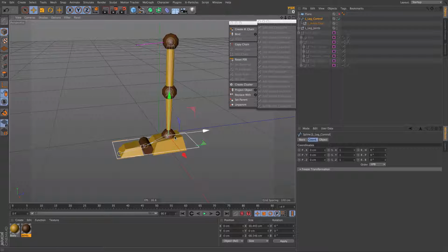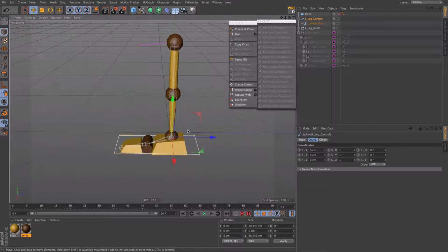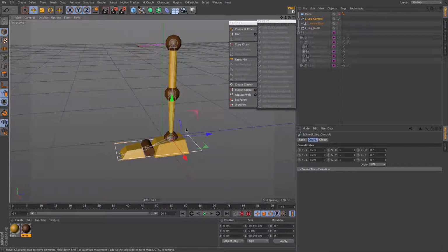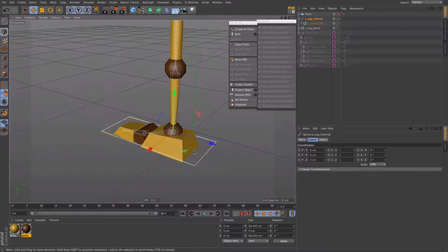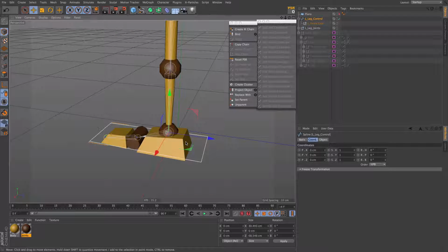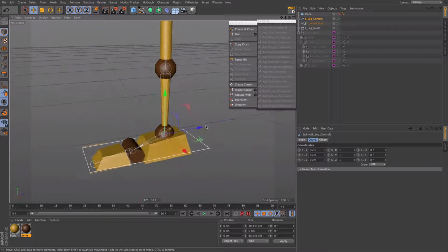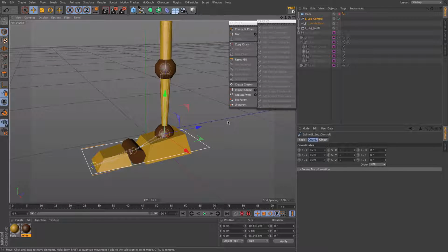Now let's make an inverse foot setup. What is an inverse foot setup? Well, now a human leg, we're used to it so much, and it's doing some very standard movements like walking, in which when we animate a walk, we would like to have some helper pivots, right? It's a very standard movement. We're going to do this a lot. And what we're going to do with an inverse foot setup is we're going to build in our rig some preset pivot points to help us with the animation.